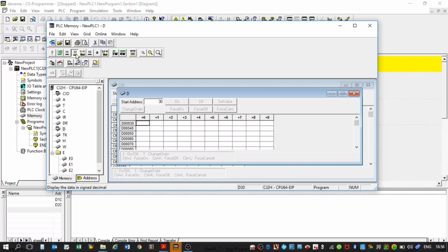But the first thing you need to focus on: let's say you have one machine and a lot of fixed parameters, maybe 100, maybe thousands of parameters inside the machine. All of them are fixed, or you have very important parameters in the machine. You can transfer these parameters after your job is finished or after you installed the machine correctly and the machine is running. You can transfer these values from the PLC and save them.